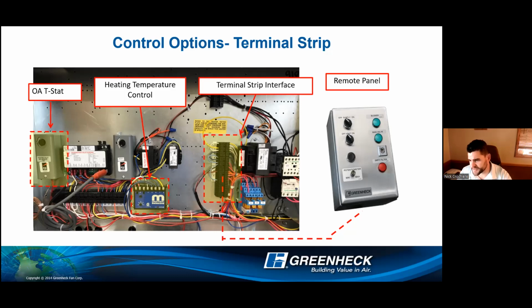You can see in detail, since it's kind of zoomed in, there is a small hole in between each block of terminals. There's 2 and 2 left to right that are all connected together. That is for actually plugging in your multimeter. You can lock it into the common, and then say you're trying to diagnose an issue with the gas train or why the unit may not be firing. You can plug right along from terminals that are normally listed 102, 103, 4, 5, 6 as you go up, and you can just sit there and probe power, power, power. And then if you don't have power, you now look at the wiring diagram. What was between the two? Now you know. So you can easily diagnose, maintain, perform startup.